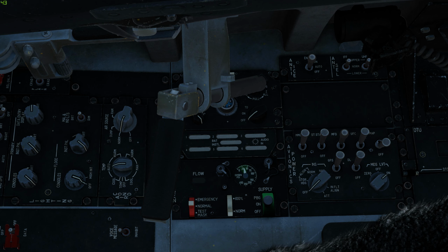The modular mission computer provides computing power to the avionics and weapon systems. Powering the GPS ensures a correct INS alignment. MIDS is the communication component of Link 16, a NATO tactical data link, and maintains TACAN functionality. TACAN volume is controlled through the Audio 2 panel. The MIDS LVT zeroize position is used to erase sensitive data.